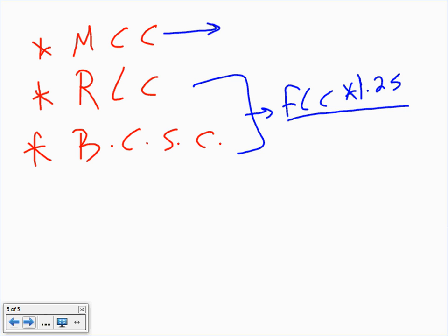This value here, I don't see a whole lot of direct importance for it design-wise anyway. Any questions, guys, about this? In the back, in the homework, they're giving you the minimum circuit ampacity and the overcurrent protection device, and they say size the overcurrent protection device and the conductor. There's a couple of questions about that. Piece of cake. Just read directly from the minimum circuit ampacity, Table 310.16. Done deal.